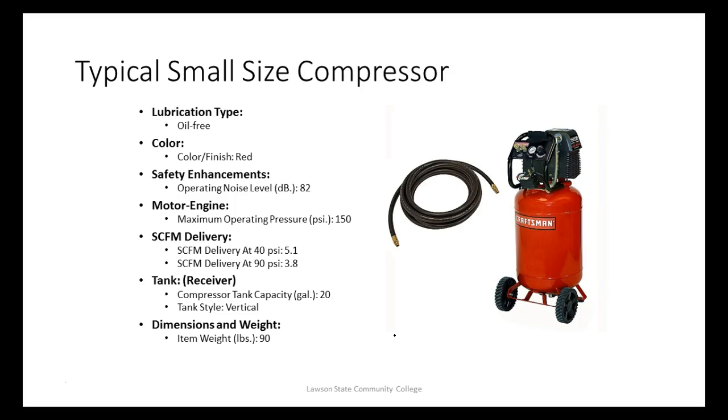Standard cubic feet per minute is what the compressor could deliver if it was operating at sea level. The problem is the higher you get up, the thinner the air gets, and the compressor can't move any more than it moves, right? You understand that? So standard cubic feet per minute means that's what this compressor could do at sea level. We could probably have some math formula to figure that out.